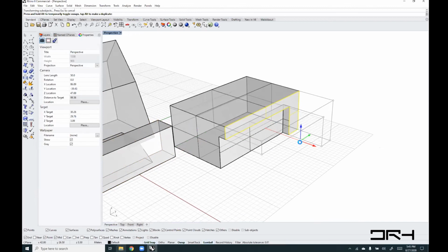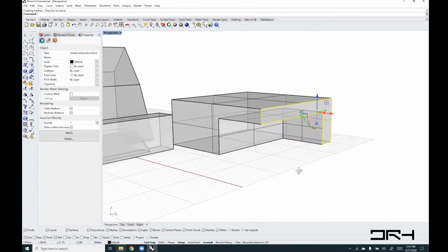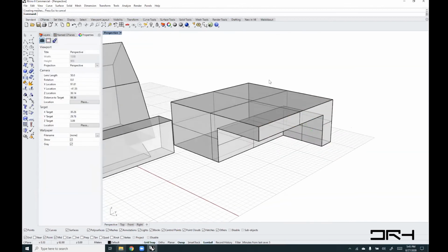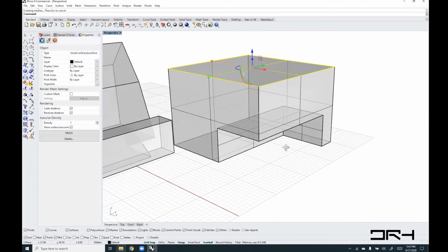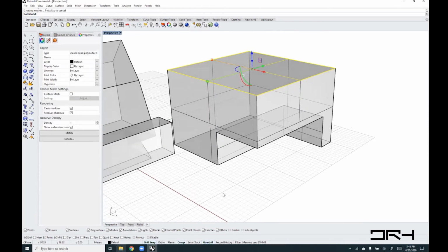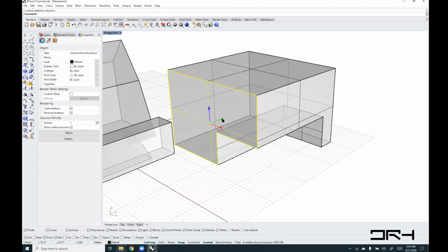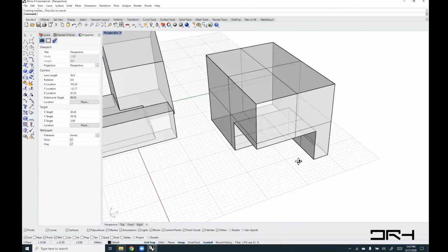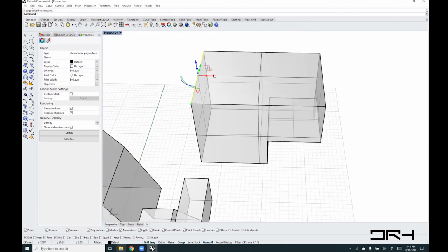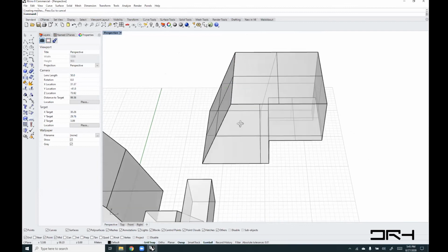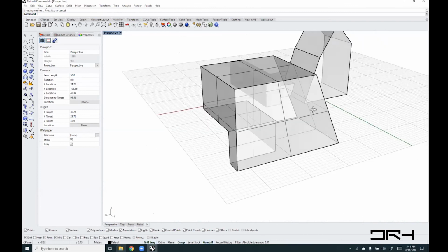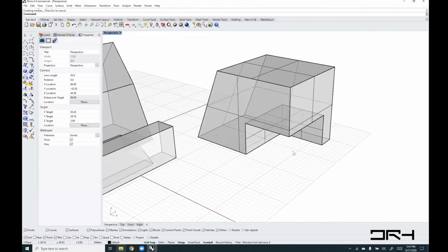And this is a really nice way to do solid modeling sometimes. You move the whole face, move it in, move it out, move some of the edges in, and you start to quickly sculpt that. But again, you need to be careful about it, because if you have faces with multiple edges, you might get into a situation.